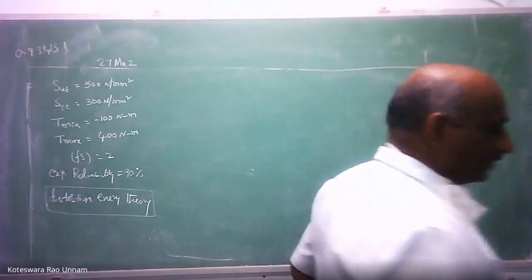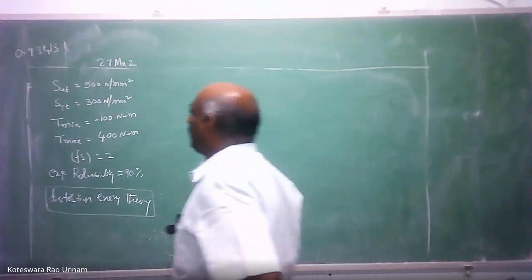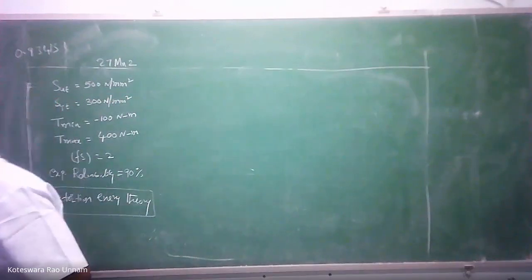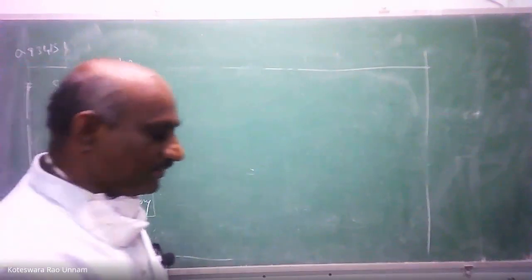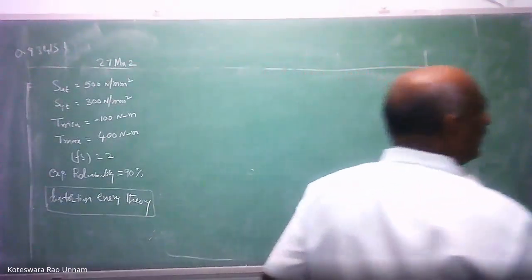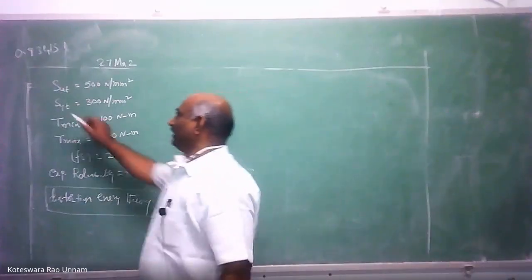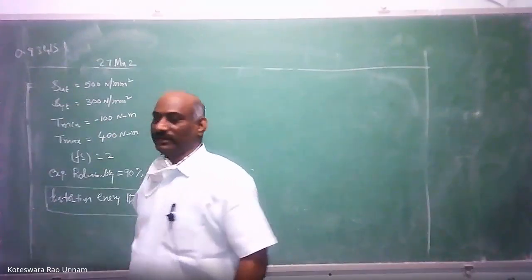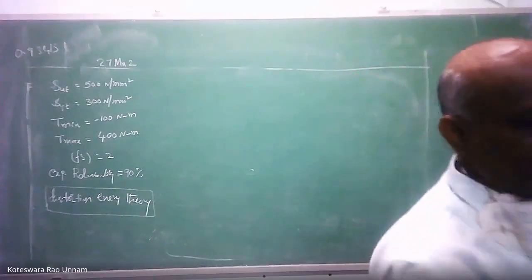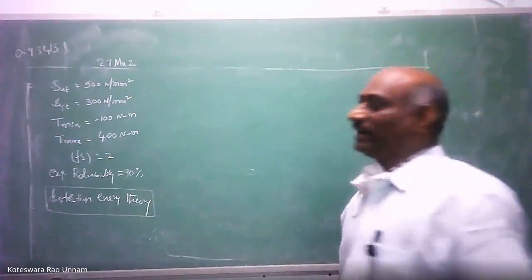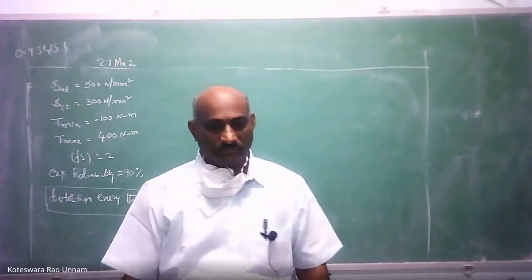all those problems correspond to either bending load or axial load. They are not corresponding to the shear stress. That's why I already mentioned at the beginning that this is a problem on torsional shear stress. In case of axial load or bending, your failure criteria are going to be either SUT or SYT. So in all the problems, whenever a material is specified, they will give you the SUT value and SYT value. So, we don't need to use this distortion energy theory.